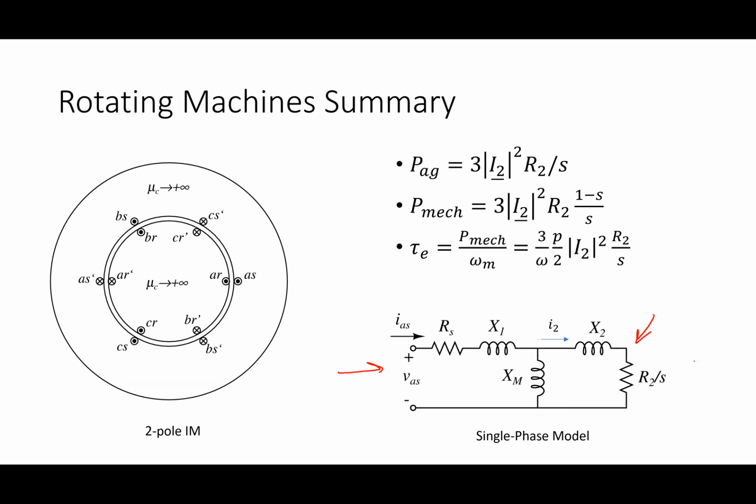I said if this guy gets all the way up to full speed, what's true about the current in the rotor? In other words, if the rotor is running at full speed, and its full speed is related to the speed of the grid, is there any current in the rotor? No. Right? If he slows down a little bit, then there's a current induced that's basically related to the difference between the 2 speeds, the difference between the speed of the field and the speed of the machine.